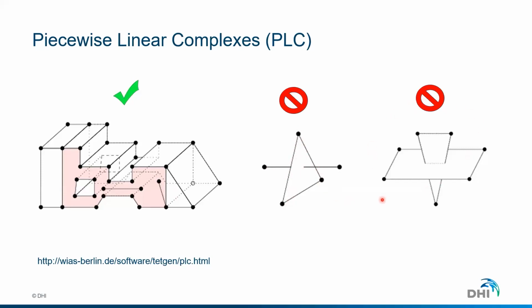The same here, if you have a horizontal geological horizon and then an intersection with another horizon or a fault, then this line has to be represented in the input data. This case is very common and happens a lot when the geological models or the geological values are exported as one single file or in different pieces. And then there is a fault model, which is also exported, but maybe with a different triangulation or resolution. So they are not fitting one-to-one, and the mesh generator will detect this problem and will not allow you to continue. So that was the situation until we introduced FEFLOW Advanced.